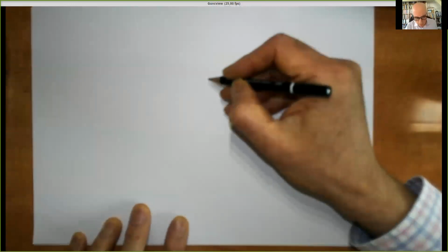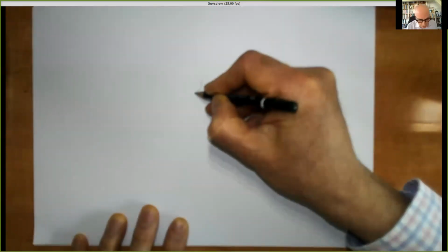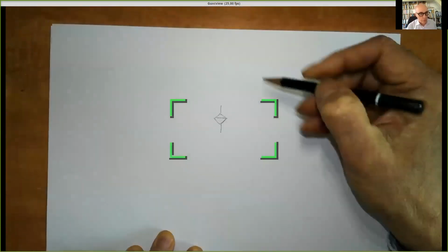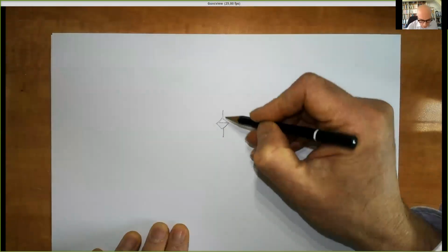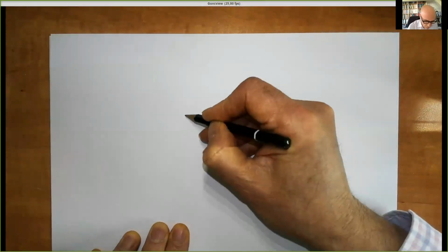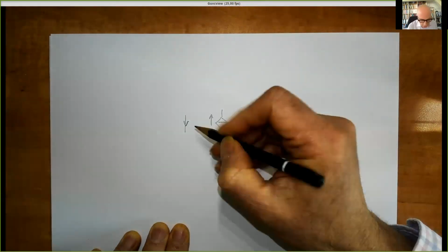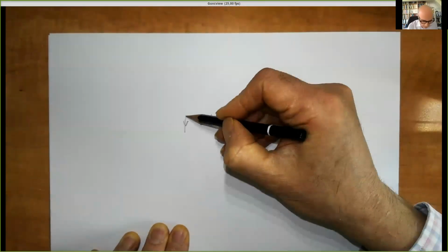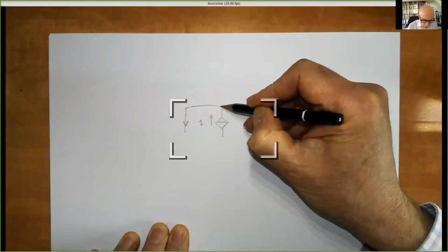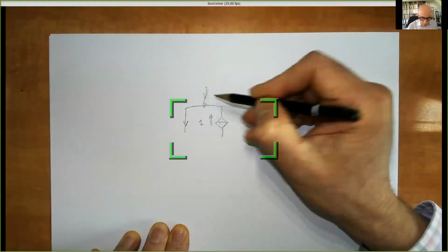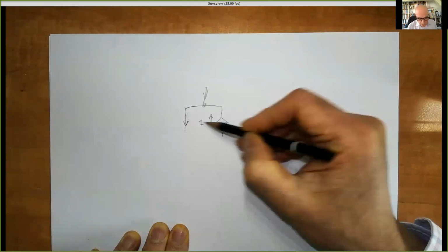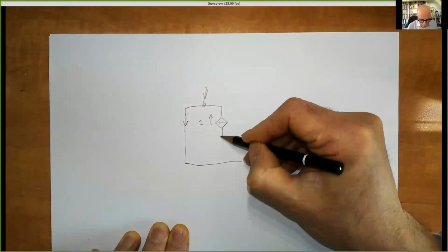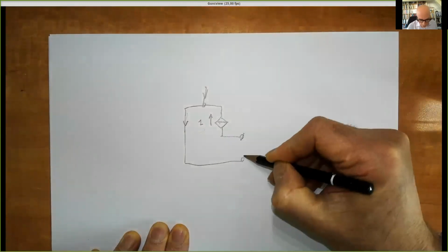Let's make a current controlled current source of which the current will be the current from the nullator. So let's say here, and I have a current gain of unity. This current is copied in this. Then I sum the two, which gives me 0 current at this point, because this is equal to this, and you see it flows like this, nothing left here. And this is my output of the nullator.